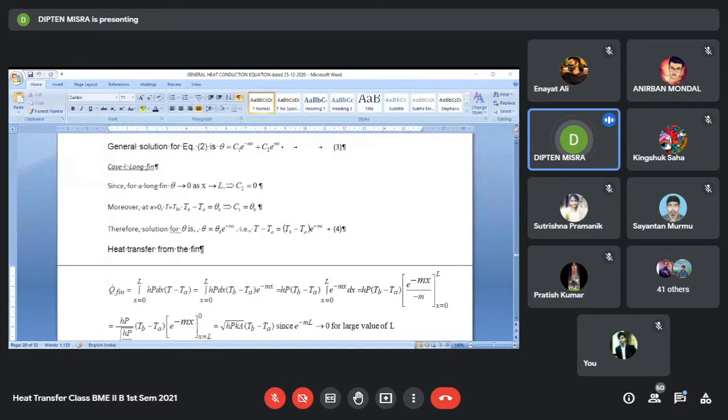Then even with a smaller temperature gradient, you can have a high amount of heat transfer. So the ideal fin is one where the conductivity approaches infinity, so the temperature gradient at the fin base approaches zero. And then you will have virtually no temperature drop along the length of the fin. So the ideal fin is one where the temperature variation will be something like this.